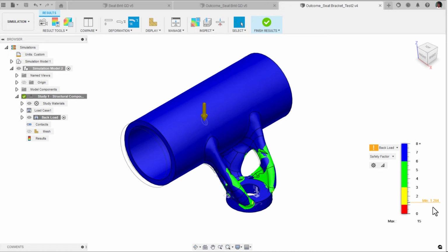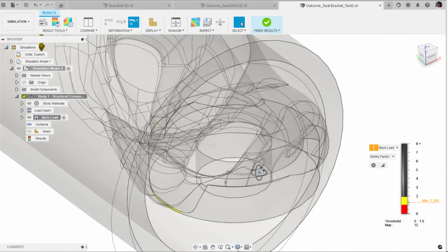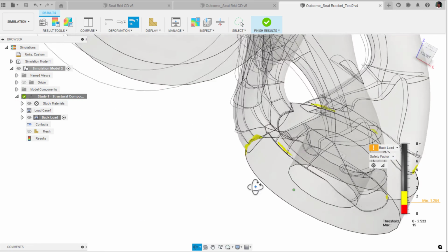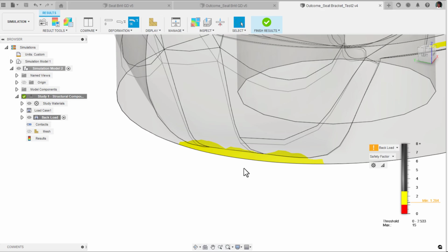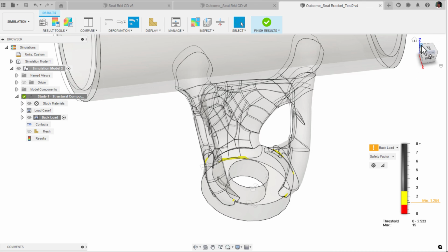So with the fine mesh we got a 1.284, and the minimum factor of safety that we set is 2. But this is the criteria of a small region. If you slide the bar, it will show the areas that were prone to this 1.284 stress. If you expand it, you can see from 3 the major area is lying. So underneath 3, there are only small areas that are prone to this kind of stress. That won't be much of a problem with our design.